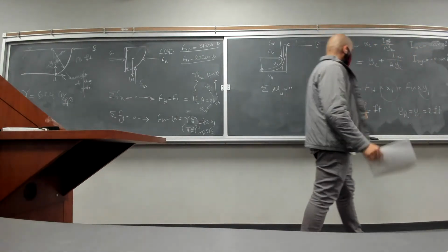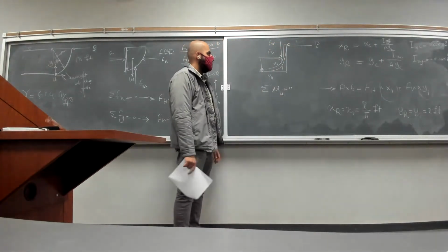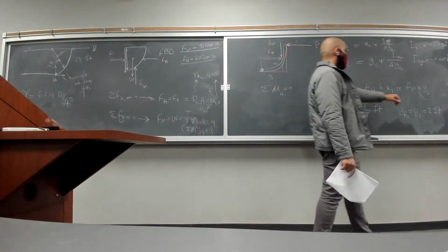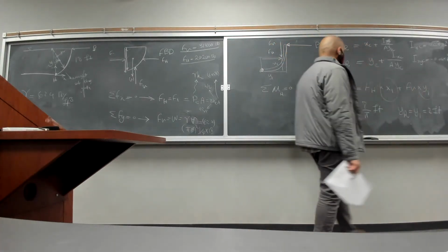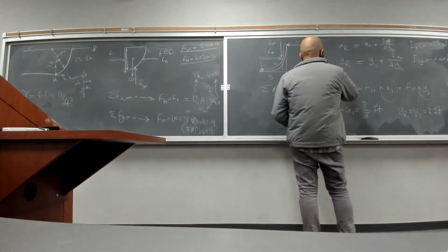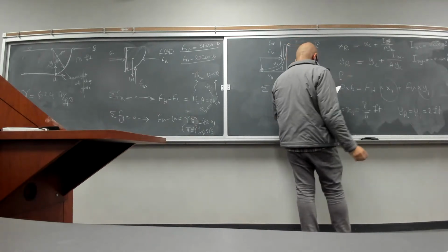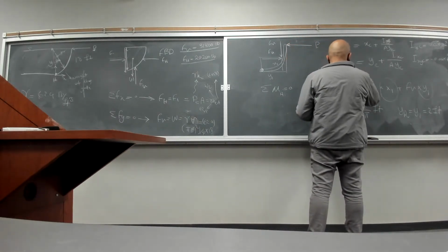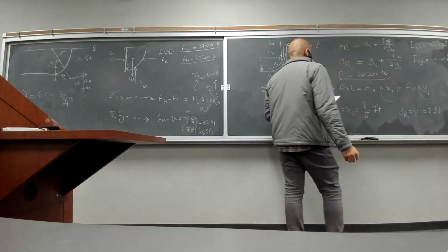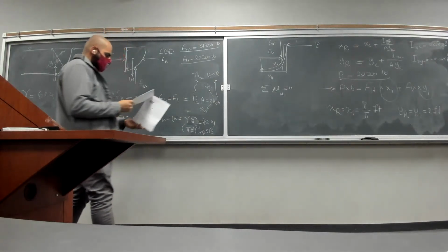These are the arms of these forces that are creating the moments on the hinge. So we have everything we need. We have FH, we have FV, we have x1, we have y1. Just plug in the numbers and you will be able to find the force P at this location, which is going to be equal to 20,200 pounds.